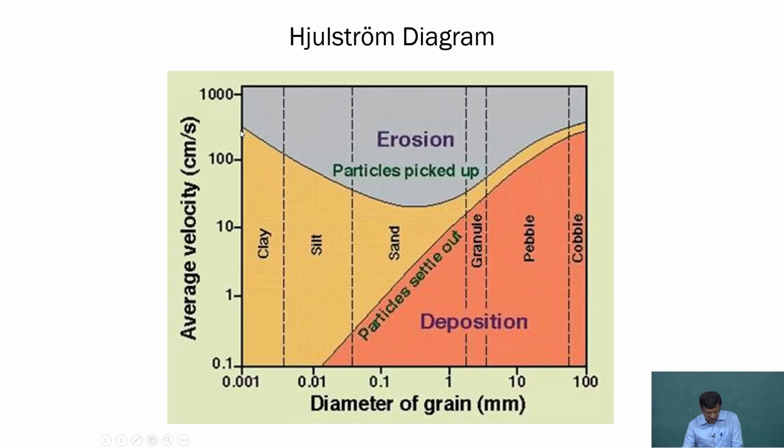So, if you look at it, it makes a maximum erosion at an optimum value, and say minor particles also will not get lifted up, because every particle needs some kind of threshold value of flow velocity to get lifted. Say, for example, a 0.001 mm particle size also requires a certain flow velocity to make it happen. Then only the erosion comes. Okay.